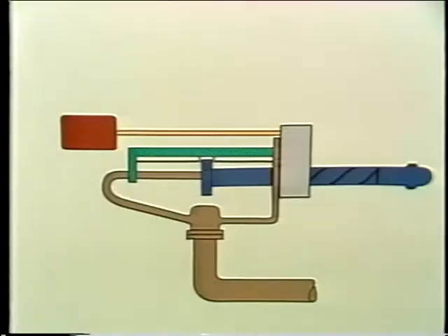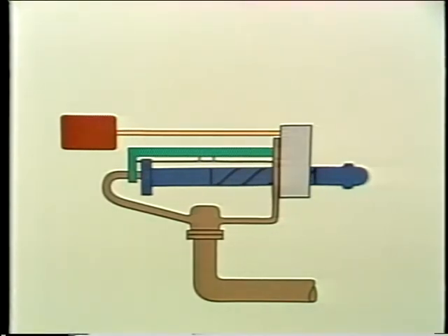A notch cut into the cam ring rides on the guide until it reaches a pawl at the end of the element's travel. This pawl releases the cam ring so the element can turn with the drive gear. After a certain number of turns, the motor drive reverses and the pawl catches the notch in the cam ring so the gear will drive the element back in. Let's see how this works in a real-life example.